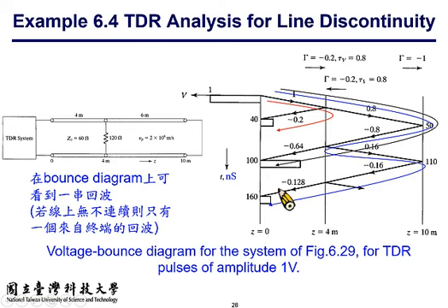So as you can imagine, every higher order term, that is, every following term that you observe, has experienced more bouncing back and forth. And because the reflection coefficients are smaller than 1 in magnitude, the energy and the magnitude of the signal become smaller and smaller.